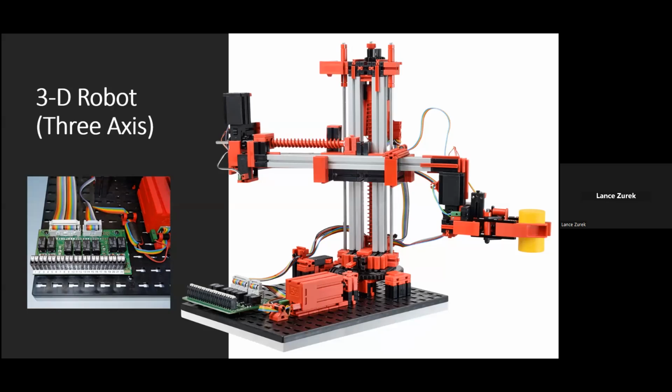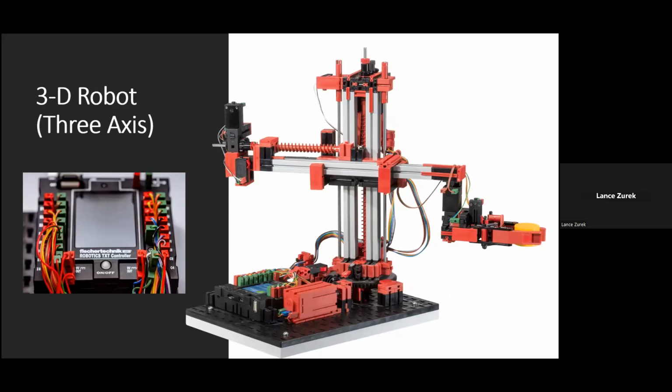Components on this model will include 2 XS motors, 2 encoder motors, and 4 push-button limit switches. Dimensions of the model are approximately 19 by 16 by 9 inches. It has a weight of about 6 pounds. Again, available in the 24-volt version with the 26-pin connector and 2.54 millimeter grid, designed for use with the PLC and programming of your choice, or available in a 9-volt version, which in this case is not a limited edition, is something that is available. It does come pre-wired to the robotics TXT controller and does require one 120-volt power adapter to power it up.